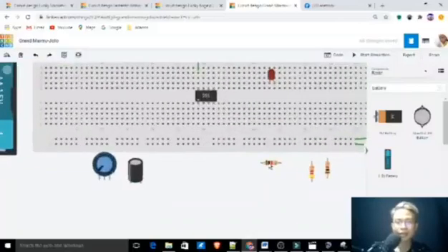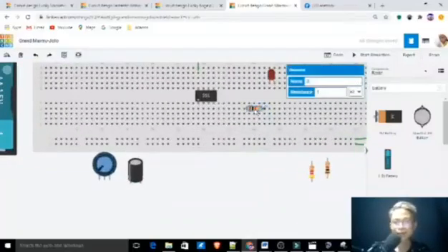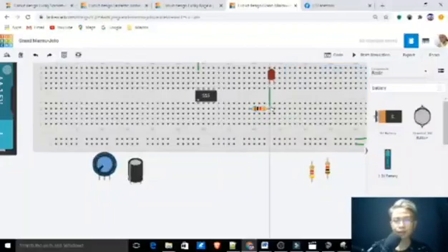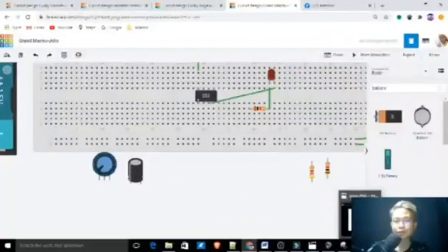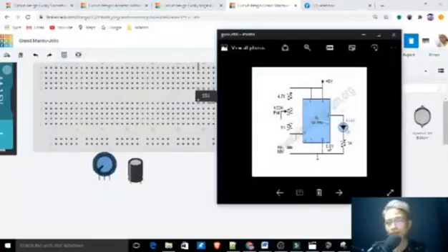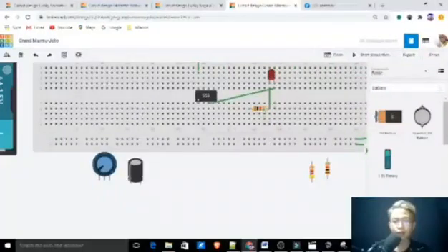From that one side, you have to connect that one here, and also this positive side of the LED we're going to connect to pin three. So here is our pin three. Let's check if I am right. So here is pin three to the LED. Another one is the 1 kilo ohms resistor, already connected to the negative side.